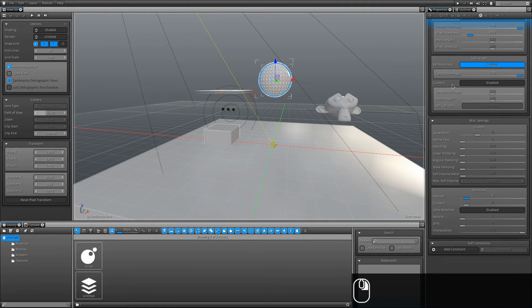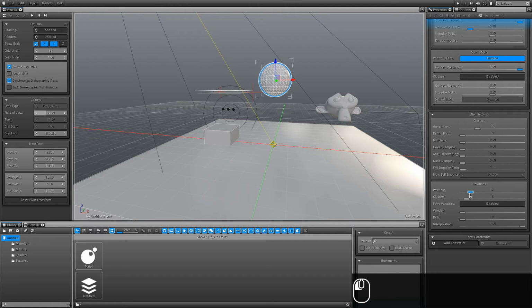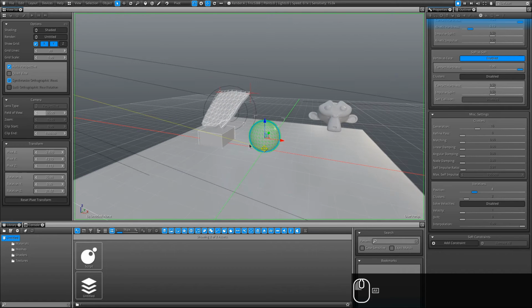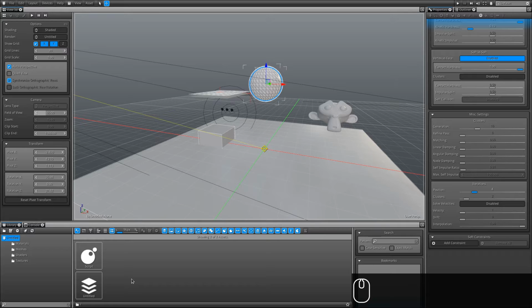We could also increase the amount of iteration to have a more accurate simulation. And the next step that we need to do is to apply some sort of stiffness to it to control the linear stiffness of this object as it is pretty stiff right now. And to do that, what we're going to do, there's multiple ways of doing it.